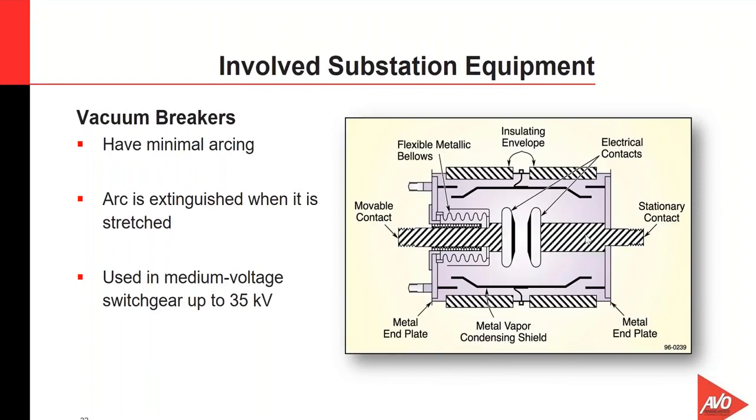Okay, this vacuum type circuit breaker utilizes a vacuum internally to extinguish arcing when the circuit breaker is opened up, and it's used to act as a dielectric to insulate the contacts after the arc has been interrupted. Unfortunately, with this type of circuit breaker, with this type of arc interrupter, when these bottles go bad, normally the operation is just to replace the bottle with a new bottle.